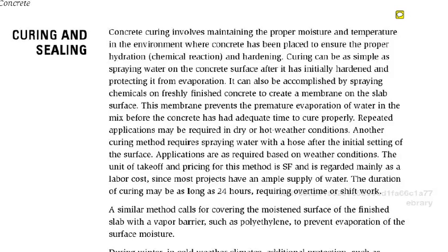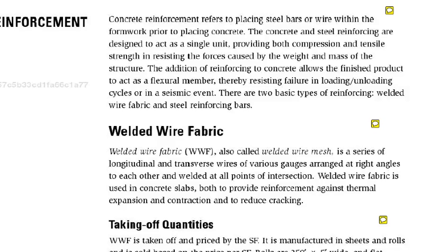Read the plans. And the important thing I mentioned right at the beginning is concrete's good in compression, and when you put reinforcement in it, it's good in tensile strength too. And there's a couple different things you can use. You can use welded wire fabric, and you often see that it's mesh. People call it a lot of things, but it has a square pattern of wires.